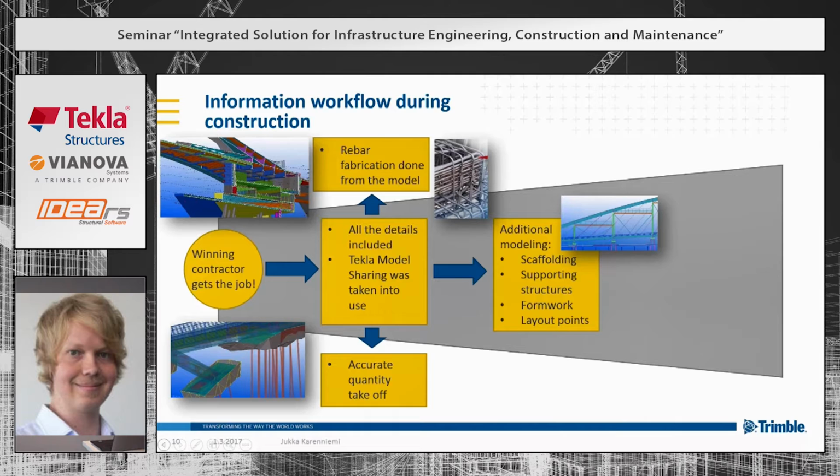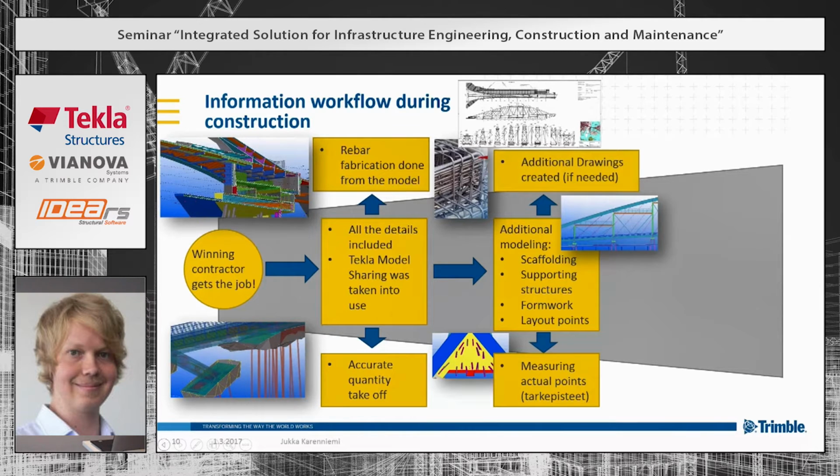So as you can imagine, it's quite an easy way to visualize and check that the supporting materials and the additional materials and modeling really are in the correct place, that they work with the design, and that they are possible to do. So that really helped the contractor. And also measuring actual points, if the piles were dislocated somehow, so they can check that the structure still works. And additional drawings were made if they were needed.